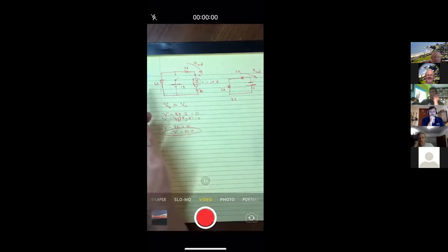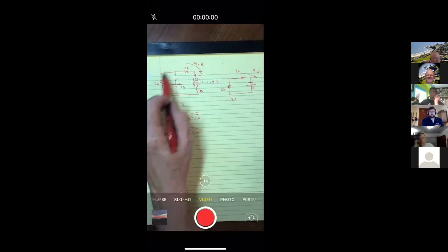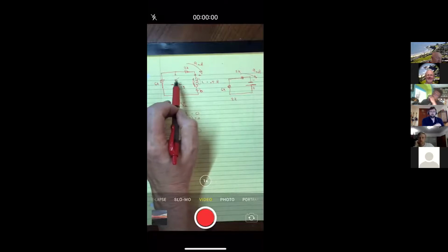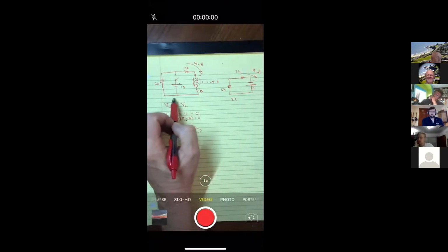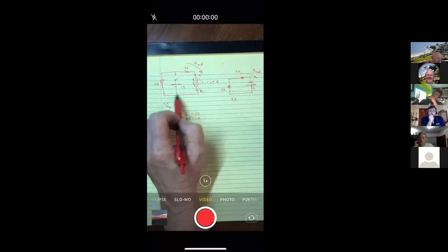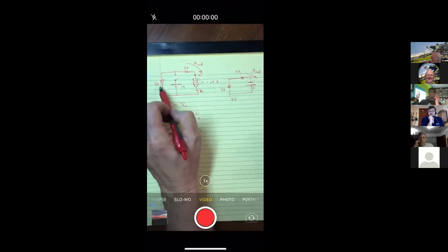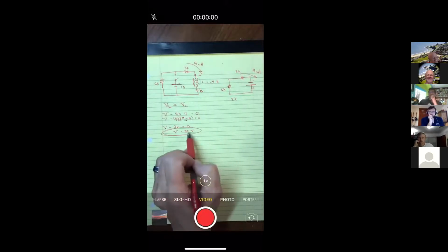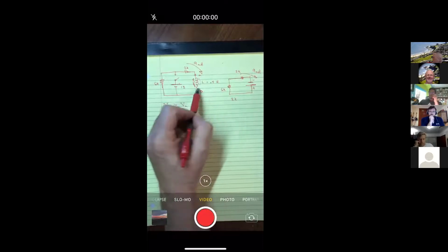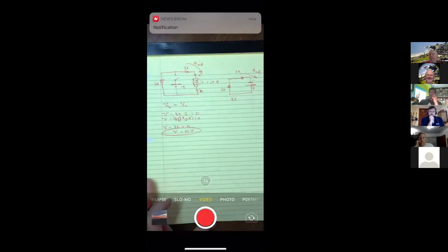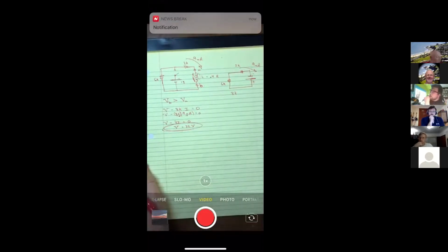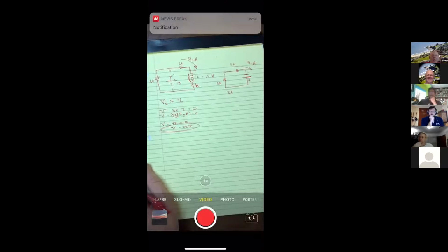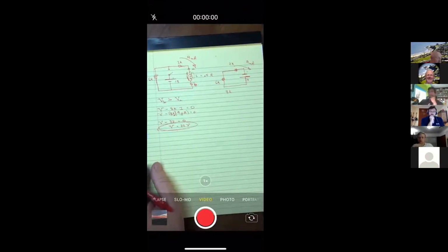When I'm designing it as the electrical engineer, I'm like, okay, how big do I make this resistor? If I make it big, that's good, because I don't drain my battery, because I'm trying to use my battery to run my drill. But on the other hand, when the operator turns it off, the higher this is, the more voltage they create, and so the more I have to make sure my motor can handle that higher voltage. So it's part of your design criteria. Okay, how do I want to do my electrical engineering here?